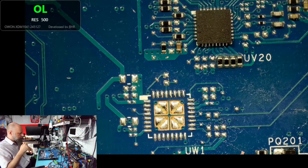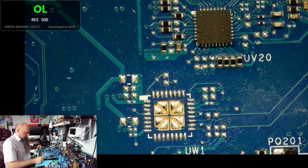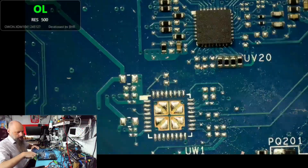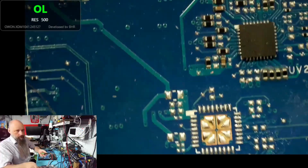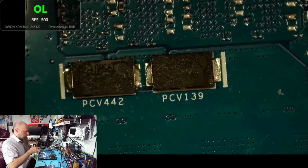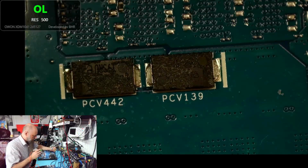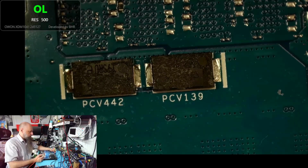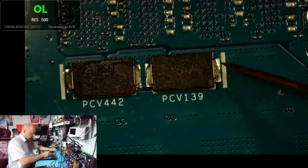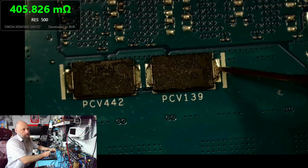Why would the GPU not be detected? So let's consider this. First, let's see if the GPU is shorted. The easiest way is to just check the vCore, the VDD, or whatever you want to call it. Basically the main voltage that is supplied to the GPU. Let's see the resistance. We have 300, 400 milliohms, right?